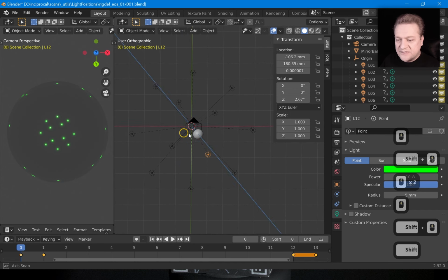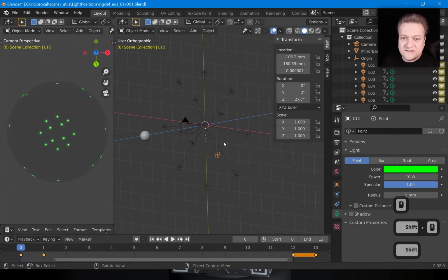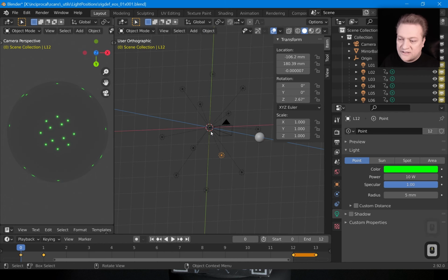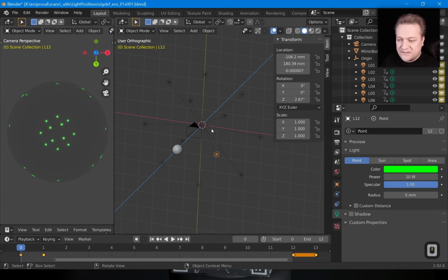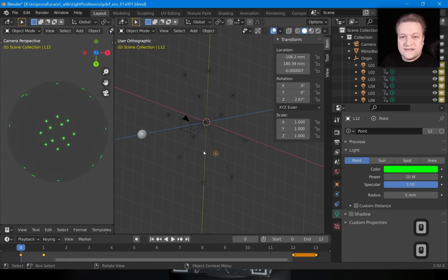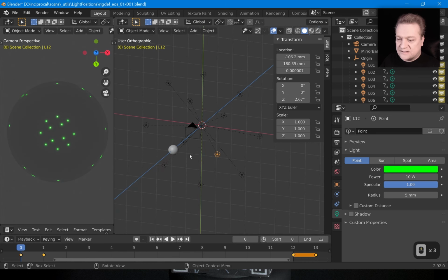If to you it might look a bit distorted, partially the reason is that when you mount the camera, if it's tilted a little bit up or down, because this is essentially a projection on the rig's grid, that whole thing might stretch. If it's tilted left or right, this thing might be a bit deformed from left to right. If the camera is tilted up and down a little bit, then this thing can be tilted as well. And this is the reason why we do this calibration, just to move things a little bit closer in place. So in this case, everything is pretty much done.